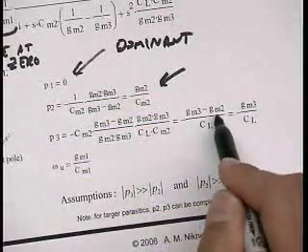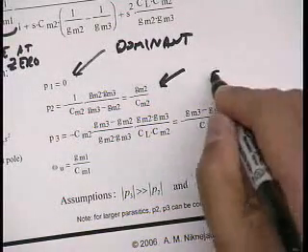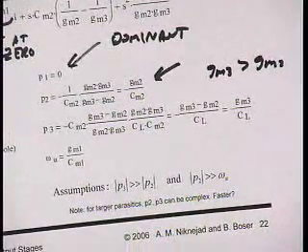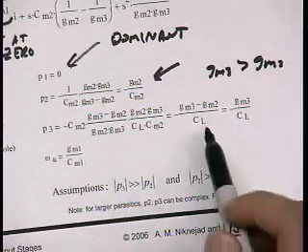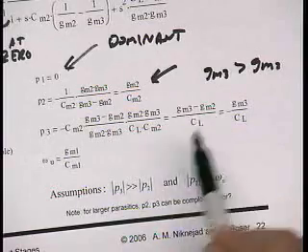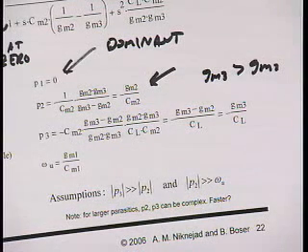And so of course I want this pole to be in the left half plane, so necessarily GM3 has to be bigger than GM2. Otherwise I get a right half plane pole, unstable system. And if you're nervous about that, if let's say I made this 10% bigger, is that a good idea? Probably not, right? Because over process and temperature, my GMs are going to vary 10%. So what if I just get unlucky and this turns out to be negative? Then I have a right half plane pole. So my yield goes way down.